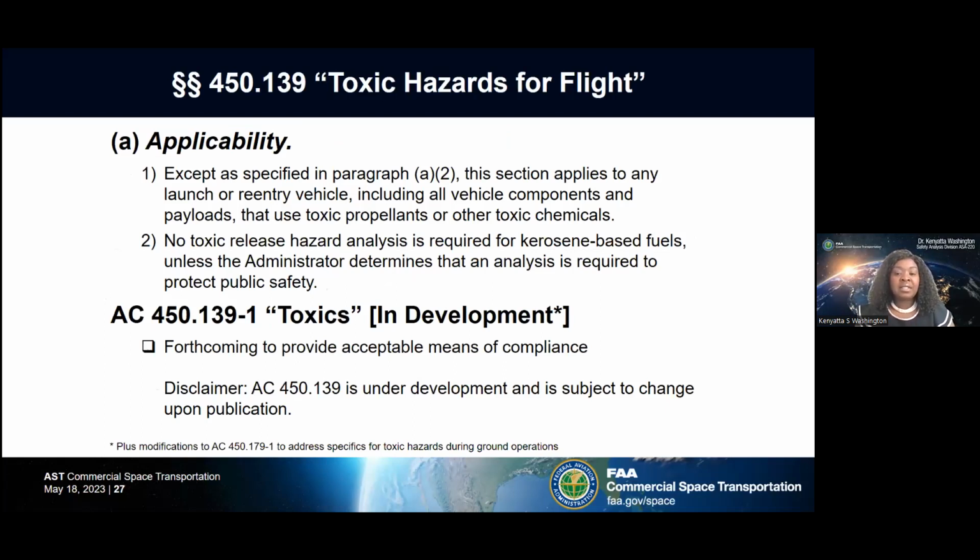For toxic hazards for flight applicability, this section applies to any launch or re-entry vehicle, including all vehicle components and payload, which use toxic propellants or other toxic chemicals. In addition, no toxic release hazard analysis is required for kerosene-based fuels unless the administrator determines that an analysis is required to protect public safety.